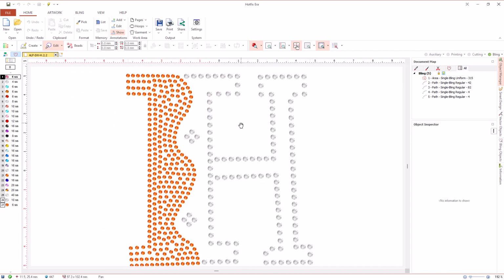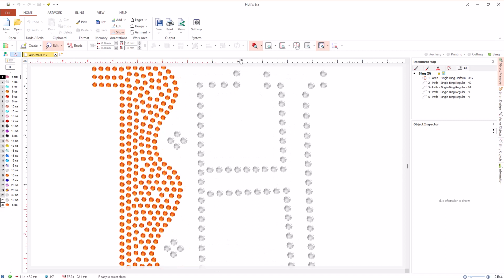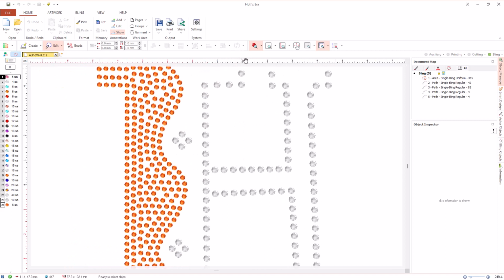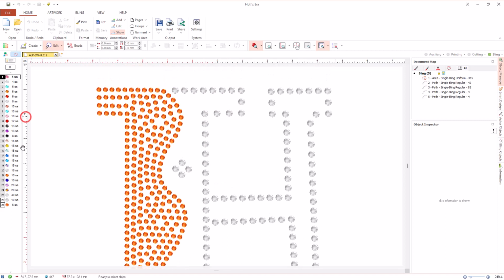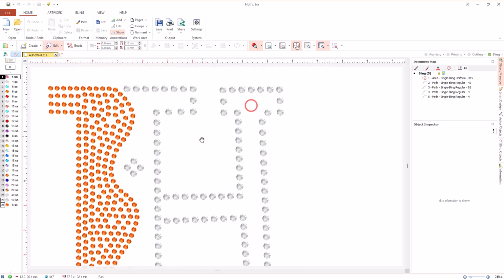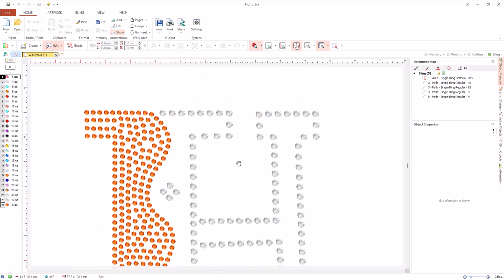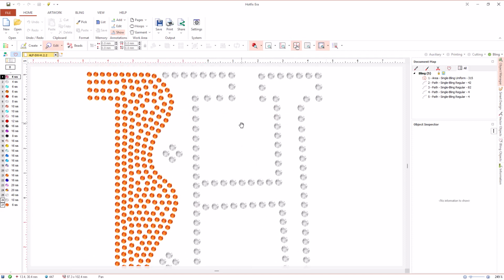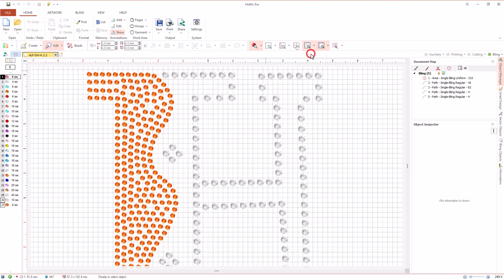An alternative way to pan is to place the mouse pointer over the rulers and drag. Some of the tools work as a mode, such as the pan tool. When activated, the system remains in pan mode until you press the escape key or open the context menu, with right-click, and select Cancel.